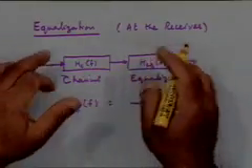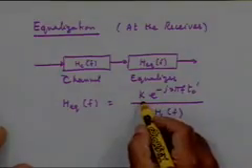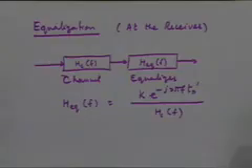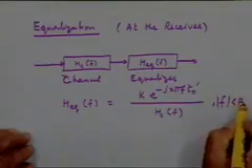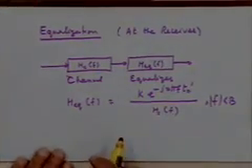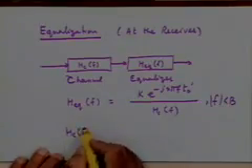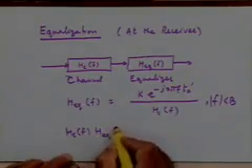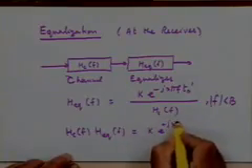The product is the net transfer function that the message will see, and it should be equal to k times e to the power minus j 2 pi f t naught prime, let's say some other value of propagation delay. Of course, this is required only for mod f less than the bandwidth. You can think of the product as some kind of equivalent channel that satisfies the ideal characteristics.